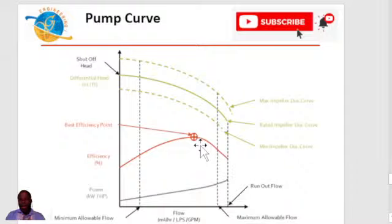flow rate. Therefore, depending upon your pump model or the design, the OEM, the original equipment manufacturer, publishes a recommended operating region between the minimum and maximum allowable flow. So they will recommend the minimum and maximum allowable operating region. You can see the minimum allowable flow and the maximum allowable flow.